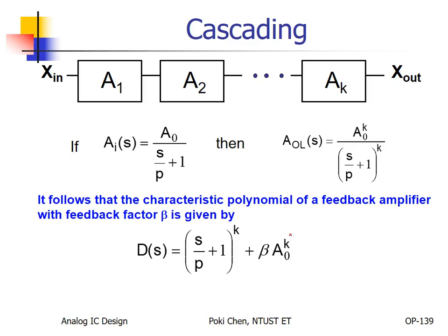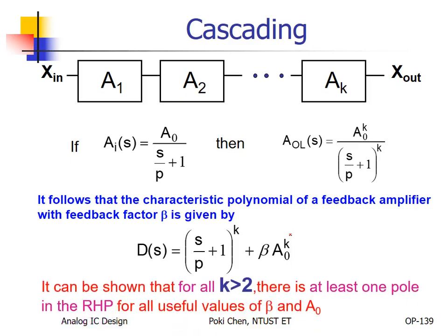Usually, we have such kind of high gain amplifier for what? To put in some kind of negative feedback loop, right? To stabilize the operation. Okay? Then something will go wrong. From the past till now, it proves that for more than 2 stages, I cannot say it is impossible, but I need to warn you.